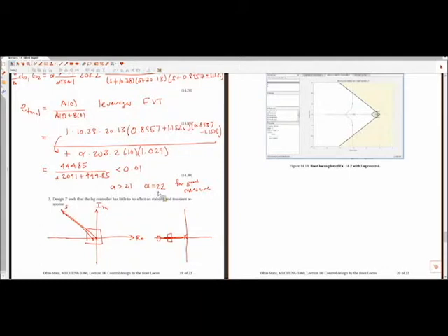All right. We also talked about how when you add a lag controller to your system, you do not want to disturb the transient performance that's already favorable. And so the question is, how do you do that? We have a pole and a zero, where the zero is 22 times as large as the pole, but we also evaluate the angle criteria for the root locus, which determines the transient response. We want the angle contributions from the zero and the pole to essentially cancel each other out, so it doesn't distort the root locus plot any.